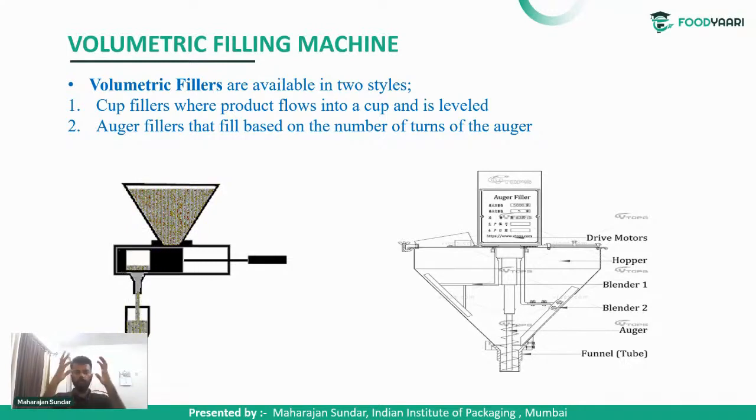It is just a mechanism which is shown in the image on the left side. Here, the product granules will be stored in the hopper. When the slot moves here and there and comes in line with the hopper, the product gets filled due to gravity. The size of the slot will be the actual size of the product which is desired to pack.